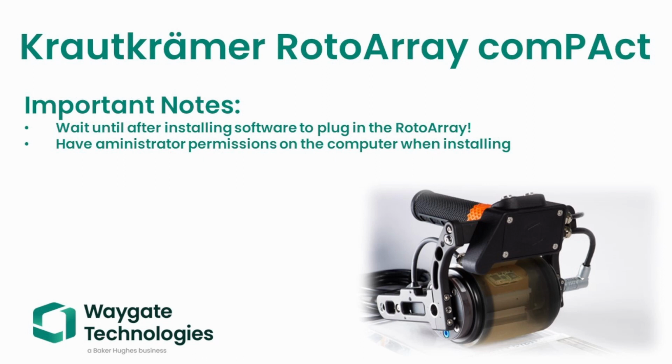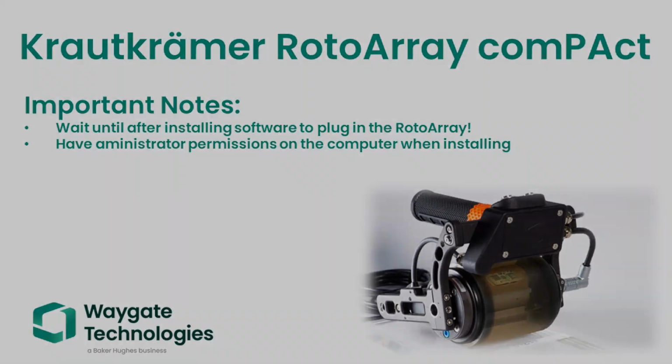The software installation process adds the hardware device driver to Windows that's needed for communications with the RotoArray. The other thing to be aware of is that because of that driver installation, you will need to have administrator or admin rights on the computer or tablet where you're doing the install. So if you have admin rights and you've held off so far patiently plugging in your instrument to the computer, you're in good shape, and now it's time to install the software.